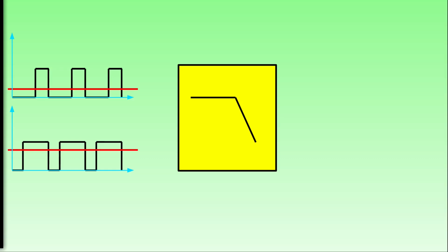Basically, a PWM signal is a square wave at a fixed frequency with a variable duty cycle. If we change the duty cycle between 0 and 1, we obtain an average value of the wave amplitude that goes from 0 to its maximum value, which is 3.3 volts for the Arduino Due. By simply forcing such a signal into a low-pass filter, we can extract the average value and therefore obtain a DC voltage proportional to the CC value from the MIDI message.